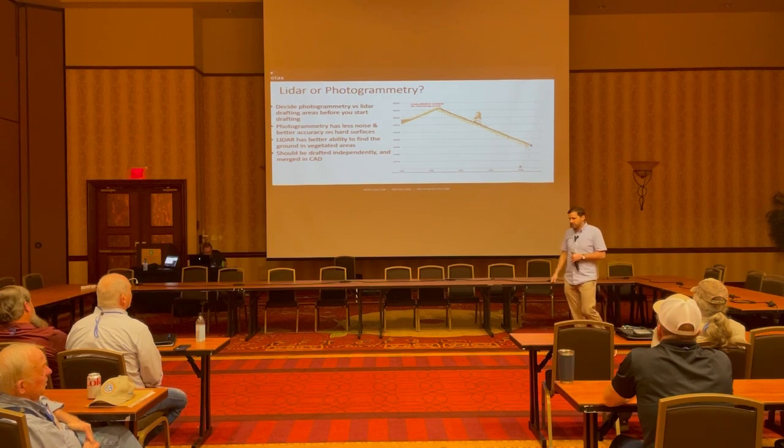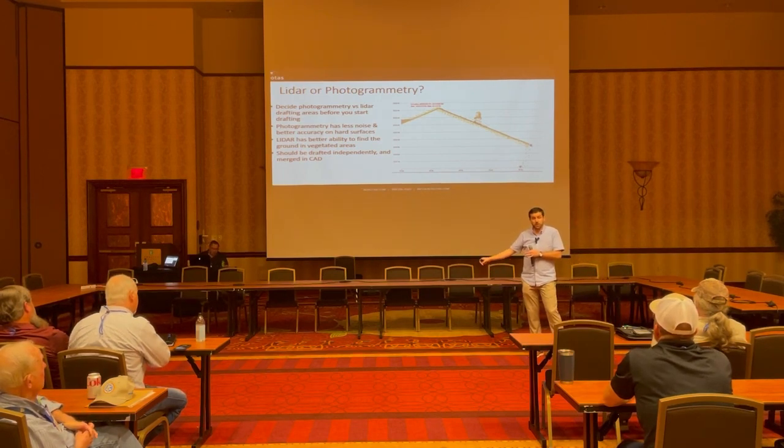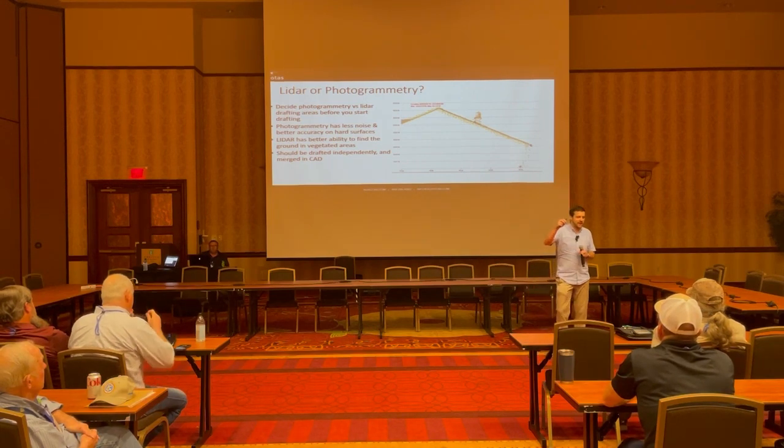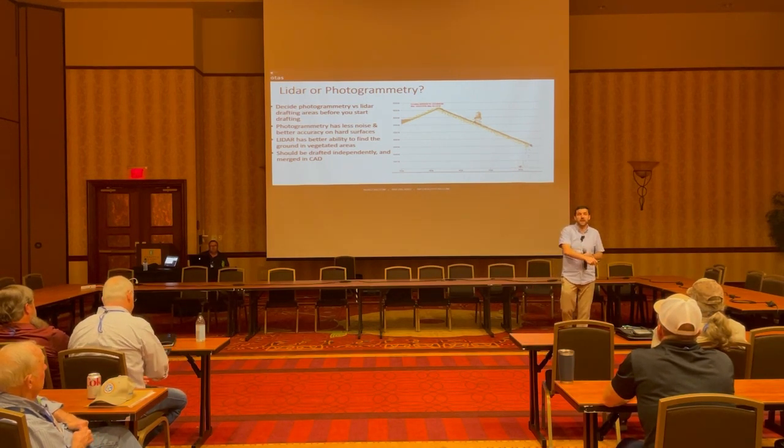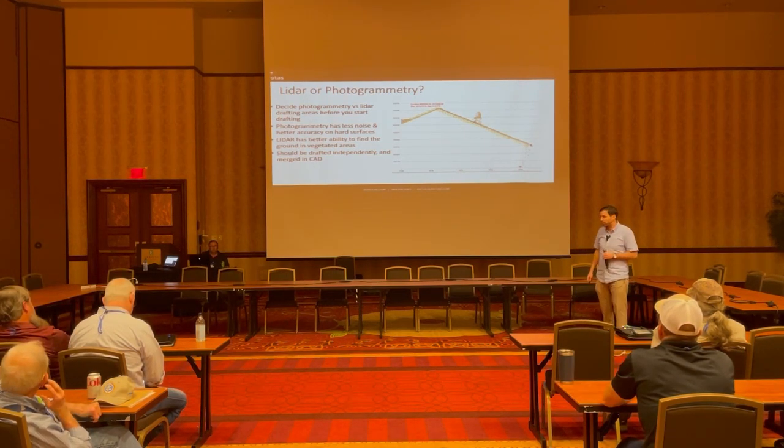So integrating a mixed workflow where you actually extract hardscape data from the photogrammetry and the imagery, and then the topo data, or topo data in vegetated areas, from the LiDAR, that's one of the most effective workflows to use, is actually a blended workflow.